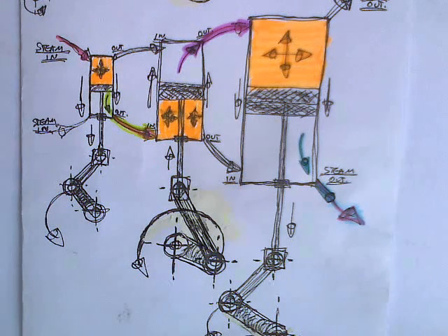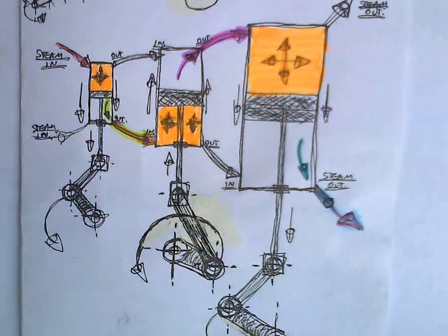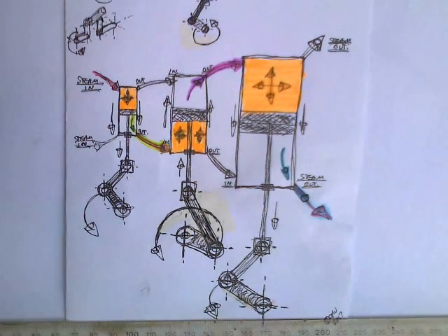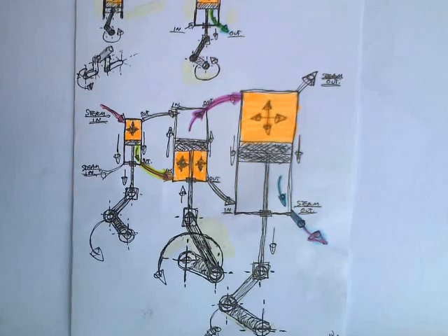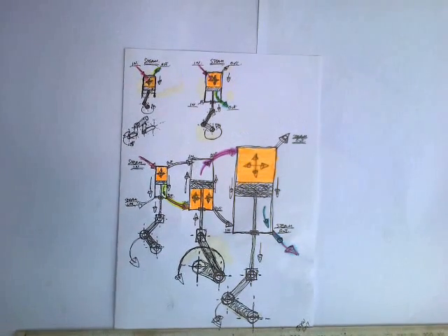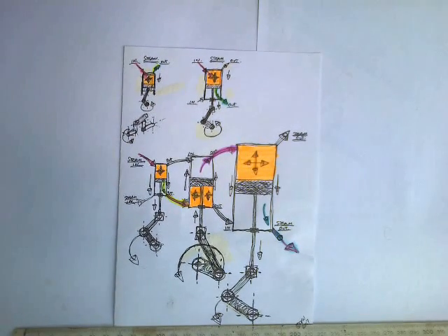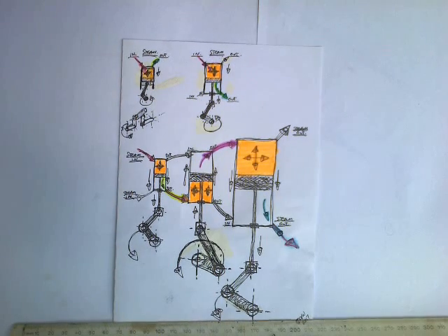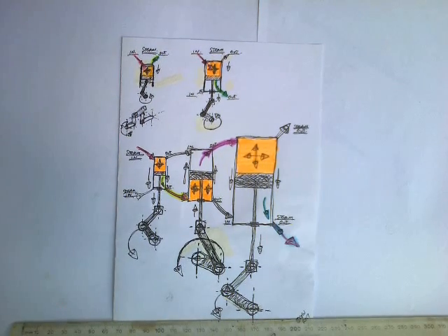But the boiler can only get 50% of the energy that's in the flue gases and put that into the water. So you've got 50% of 35%. So the most efficient mechanical, reciprocating, piston type steam engine was only 17.5% overall efficient. And that's not good. You know, like my car engine's 25% or so.